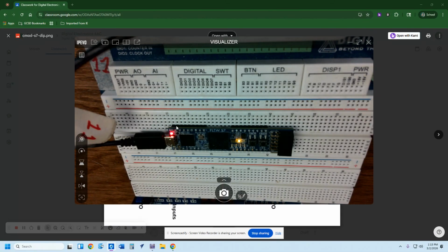There are little plastic black blocks here underneath the chip. Those represent the actual connections to the board. So again, 21 and 22. This is 24, that's 23, there's 22 and 21. So basically, I'm going to run some wire from there, and I'm going to hook those up to my switch access point here. The switches are down at the bottom of the board, okay? But these are going to send a signal into the chip, and then the chip will send a signal out to an LED. So let me grab some wire here.